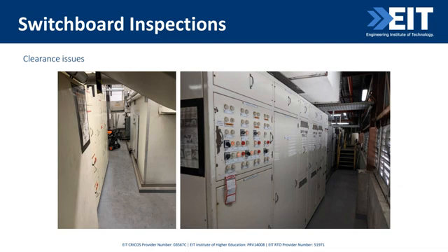Maybe you have clearance issues, such as we've shown here. If you think back to that diagram, opening all these doors is going to block this narrow hallway, so we don't have enough clearance from here to here. Similarly on this side, we check our existing clearances here. Obviously this has a fault sticker indicating something's locked out and might show to us that there's a problem.